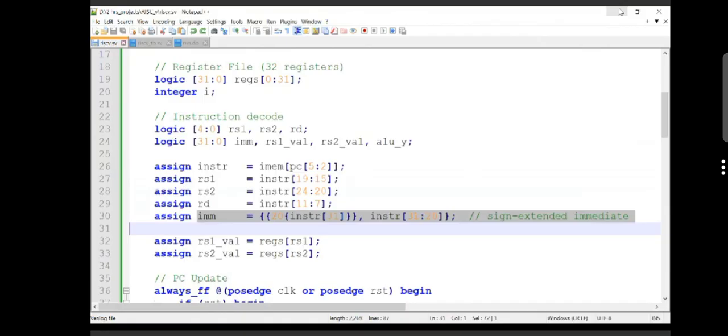Your I value is 20, and next it needs to get the instruction bits from 31. In that, 31 to 20 it needs to get from this. Here 31 to 20 are all zeros, so it will take zeros itself. That's why it is becoming this value.